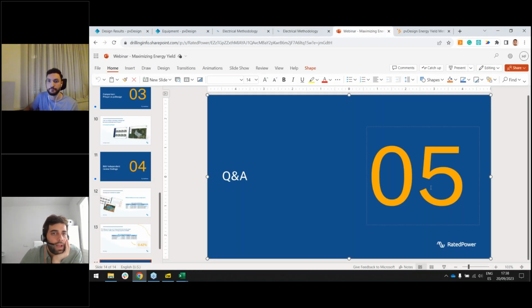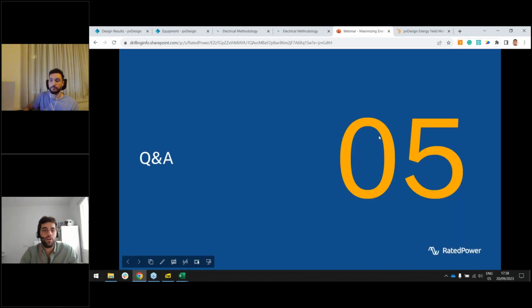Great. I have noticed that the DC-AC ratio is not always the same in PVsyst and in pvDesign. Why is that? Yeah, actually, this is something that we do get asked a lot. Sometimes it might be the same. Most times, probably it will not be the same. The main reason behind this is a definition of how we calculate DC-to-AC ratios. In our tool, when we take the AC capacity, we take the Pmax of the inverter. Because of that, we are also using the Pmax of the inverter for calculating the DC-to-AC ratio. Whereas PVsyst, if I'm not mistaken, always takes the Pnom. Thus, the value over there will be slightly different.